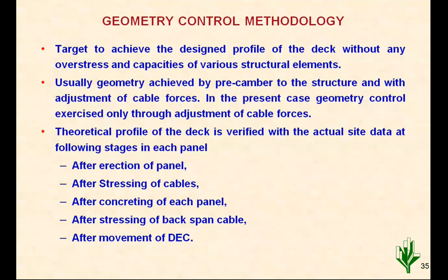That can be achieved by pre-camber, but here the decision was taken that pre-camber in steel girders was difficult. Otherwise, the bolt matching, etc., may mismatch, and so the decision was taken that pre-camber will be done using cable forces only, and accordingly the cable forces were analyzed, and those were applied in the cables. So the theoretical profile of the deck is verified at each stage.